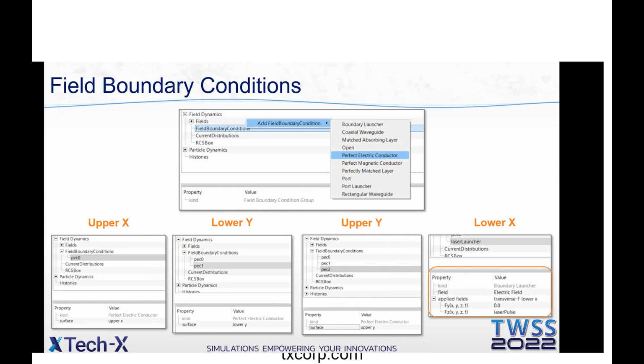Well, one place you need those is if you have a very high magnetic permeability material, like mu material. In that case, when you put that in the simulation, you want the magnetic field... It basically almost acts like a perfect magnetic conductor. There's no perfection in the world, of course. There are no perfect magnetic conductors, no perfect electric conductors, but that is a common approximation that works very well.